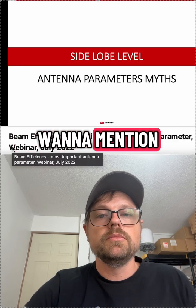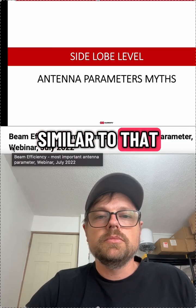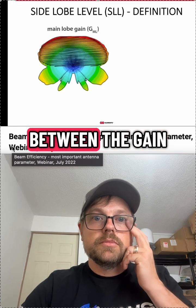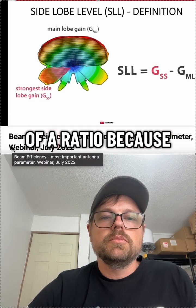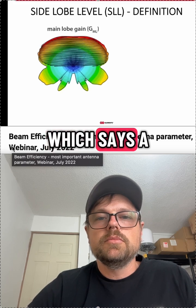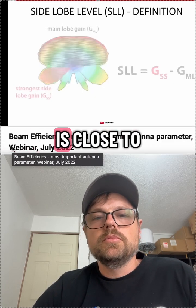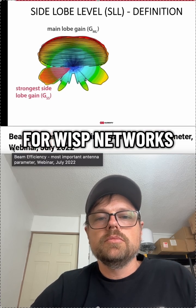Another parameter I want to mention is side lobe level. In practical life, its effect is similar to that of the front to back ratio. Let's have a look at the details of that. Side lobe level is the difference between the gain of the strongest side lobe and the main lobe. It is more useful than front to back ratio because it at least points out the strongest side lobe, which says a bit about antenna performance in high noise areas, but just a little bit really. If side lobe level is high, the strongest side lobe is close to having the gain of the main lobe, making it a very poor antenna for WISP networks.